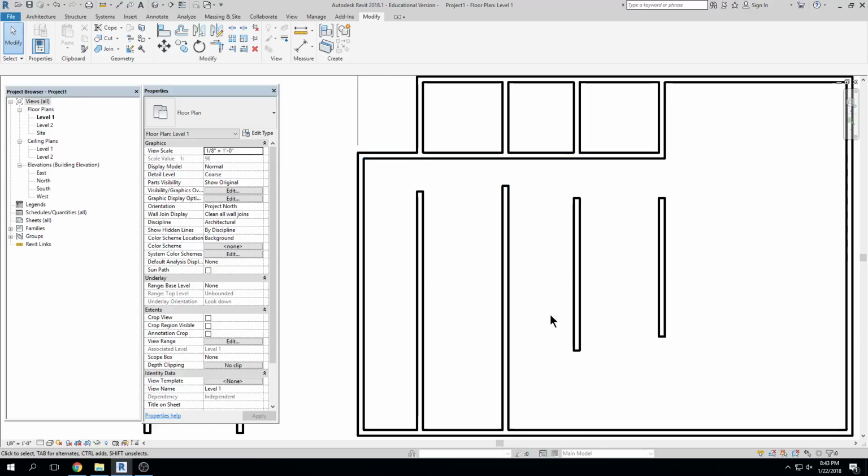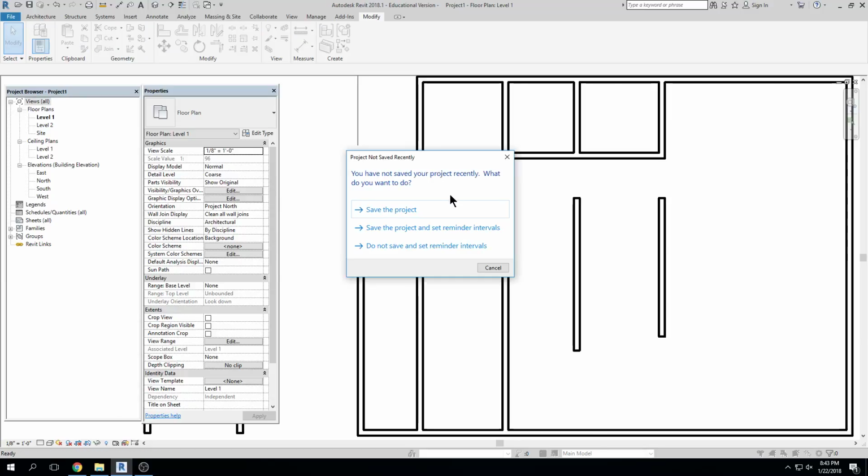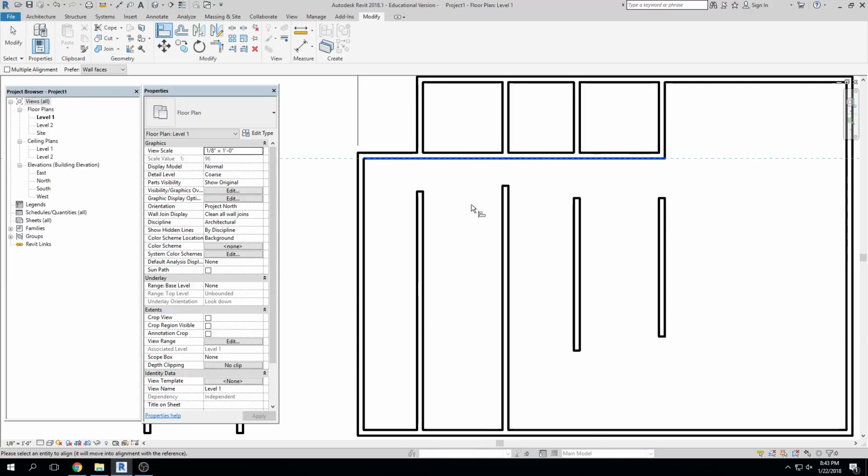We're going to start thinking about our commands a little bit differently. In AutoCAD, you would extend: EX, enter, enter, and you would extend our lines up. But in this case, we're just going to start aligning objects. So AL, click, and I want them to align here, right? Click. Now this kind of alignment, where I have one established point and I want all of these to go to that established point, is a multiple alignment.